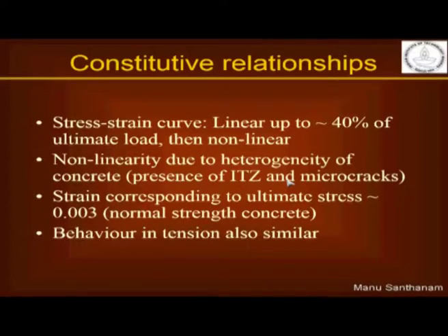What turns out in concrete is that the behavior in tension, in terms of the non-linear stress strain behavior, is similar. Obviously the stresses and strains in tension are going to be much smaller as compared to the stresses and strains in compression. That is what you need to remember: the overall shape of the stress strain curve will be similar, but the values of stresses and strains will be quite different in the case of tension.